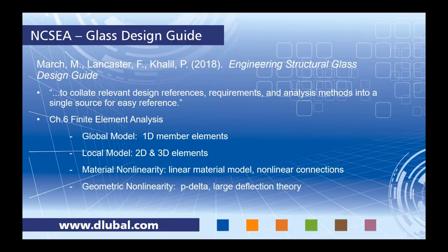As far as material nonlinearity, the design guide states that glass is a linear material model. Well, we also consider it an isotropic linear elastic material, but that nonlinear connection should be considered. Now, this might be more relevant for something like point-supported glass. We can also take into consideration these nonlinear connections with things like contact solids, and we don't have time to focus on something like point-supported glass connections today, but I do plan to do a follow-up webinar sometime within the coming months to maybe more focus on this.